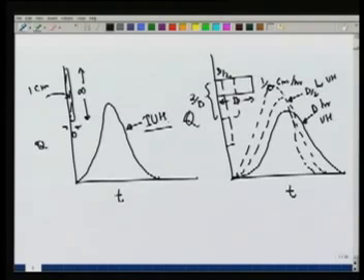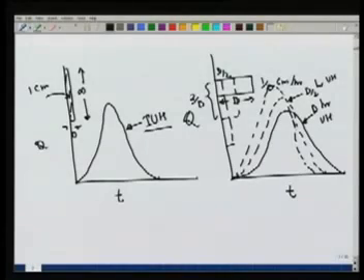So as you can see, there is no duration attached with IUH. In unit hydrographs we had a d hour unit hydrograph, for example it may be a 6 hour, 4 hour or 2 hour unit hydrograph, but IUH is for instantaneous precipitation with total depth of rainfall equal to 1 centimeter, or sometimes people take 1 inch. So our aim is to derive this IUH and then use it to analyze the direct runoff due to a non-uniform storm. So let's first see how we can obtain the direct runoff due to a non-uniform intensity distribution.